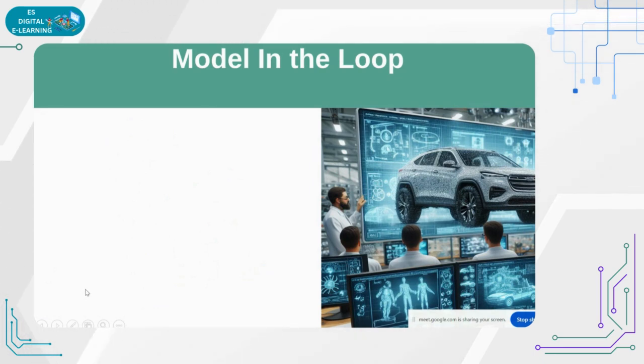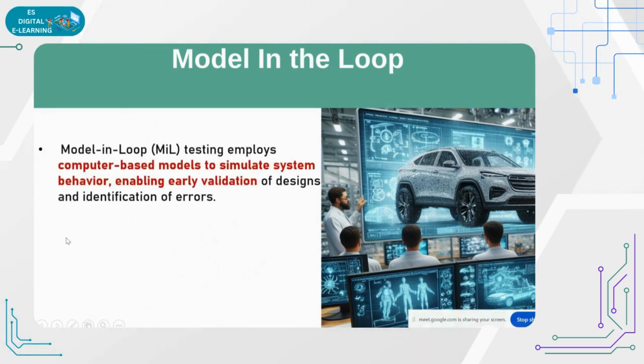Yes, sir, that particular ECU only we are connecting in that hardware loop, and we are testing. Yes, we are connecting the particular ECU, because we need to test the software, right? So that's the reason. We are not testing the ECU, we are testing the software present in the ECU. We need to check that software behavior, whether the braking is working or not.